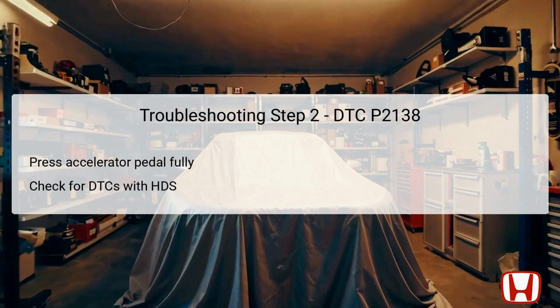In the second troubleshooting step for DTC P2138, the next action is to press the accelerator pedal down to its full extent. This action helps simulate conditions under which the APP sensors operate, allowing the system to gather data on their performance. It's necessary to have the HDS connected, as it will assist in checking for any pending or confirmed DTCs that may red flag additional issues. After pressing the pedal fully, the technician should look for the presence of DTC P2138 again.